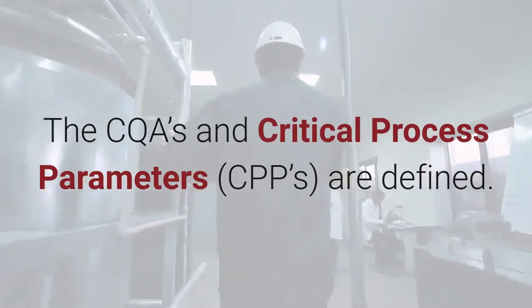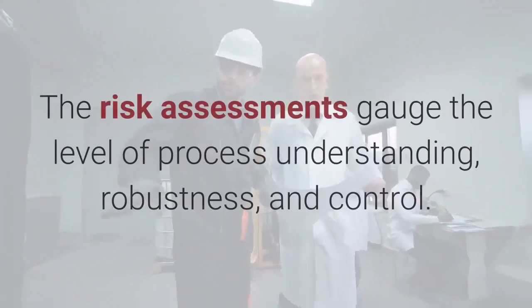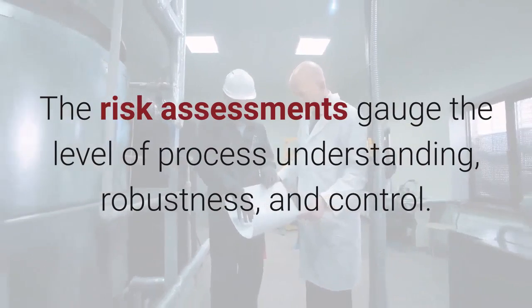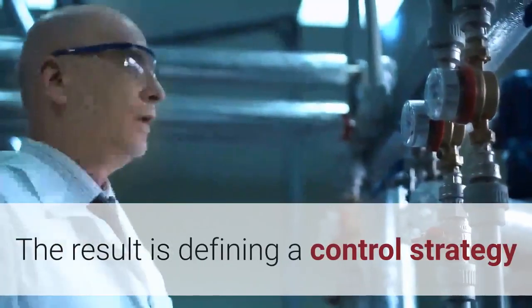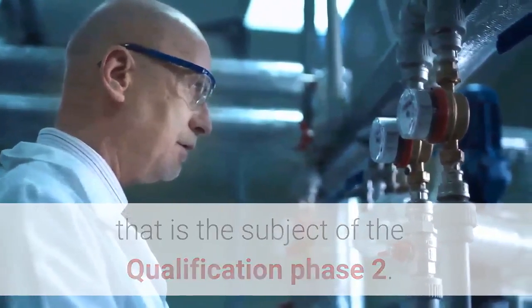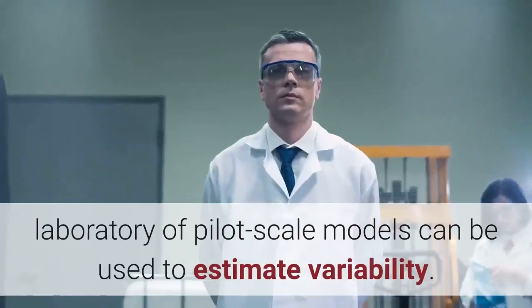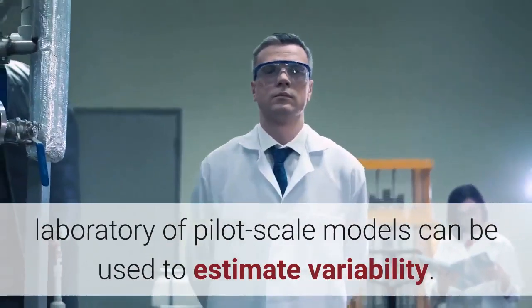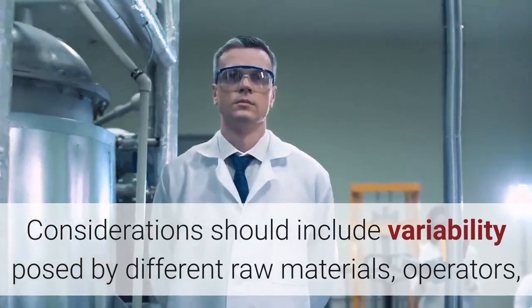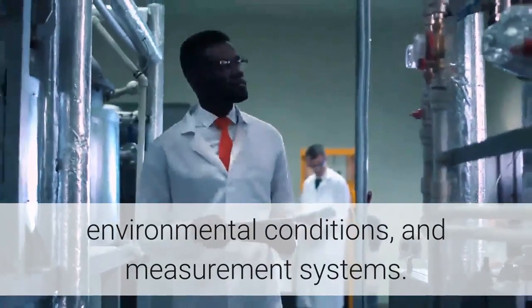The CQAs and critical process parameters, CPPs, are defined. The risk assessments gauge the level of process understanding, robustness, and control. The result is defining a control strategy that is the subject of the qualification phase 2. Although the full spectrum of input variability is not known at this stage, laboratory or pilot scale models can be used to estimate variability. Considerations should include variability posed by different raw materials, operators, environmental conditions, and measurement systems.